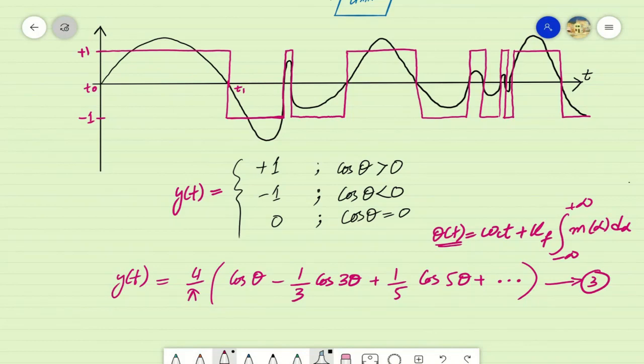So the first part of this expression has theta in the phases, so we'll generate a certain frequency band where omega c will be its central frequency, and the second part of this expression will cause deviation in its frequencies, while the peak deviation we have represented with delta f was proportional to both the constant scaling factor kf and the peak amplitude of the information signal.